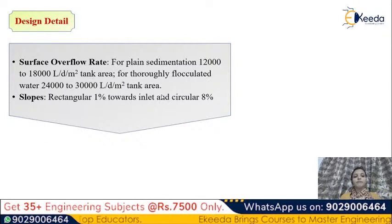And slope should be maintained for the rectangular sedimentation tank. It should be 1% towards the inlet, and for the circular sedimentation tank it should be 8% towards the central part or the inlet.